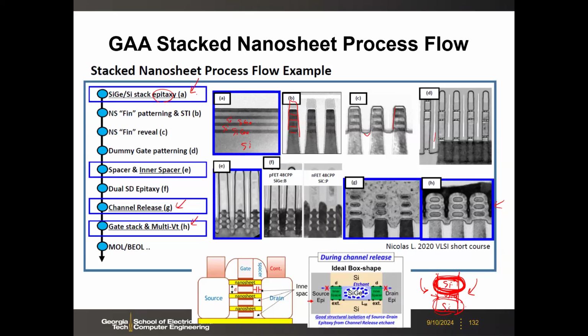That's a good question. I think it's because of this epitaxial growth. And yes, it's similar to silicon. And then you can have the lattice match. And also the chemical solution attacks the silicon germanium rather than the silicon, then you can have this release process.